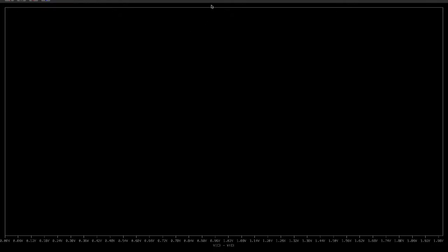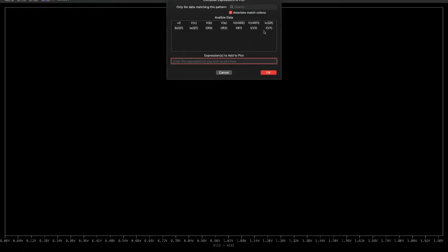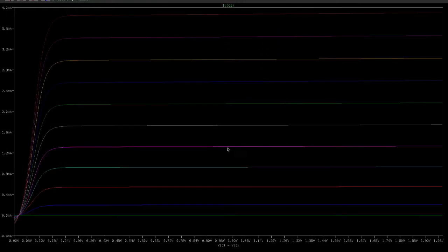Okay, and then let's add our trace. So we want the current through our collector. So that's typically what we plot. So Ic(Q1). Okay, and there we go.